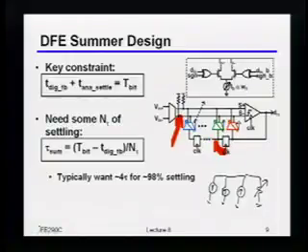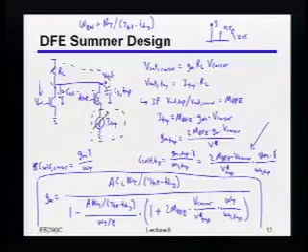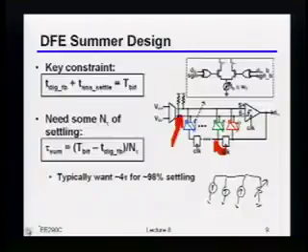Question. Yeah. If you keep the switches in saturation, why do you have nonlinearity? Because their RO is not infinite. Which RO are you talking about? Just the RO of the current steering switch, of this device. Right? Or the other picture of these devices. Right? Oh, you're just saying the nonlinearity from the GM and RO of the transistor?